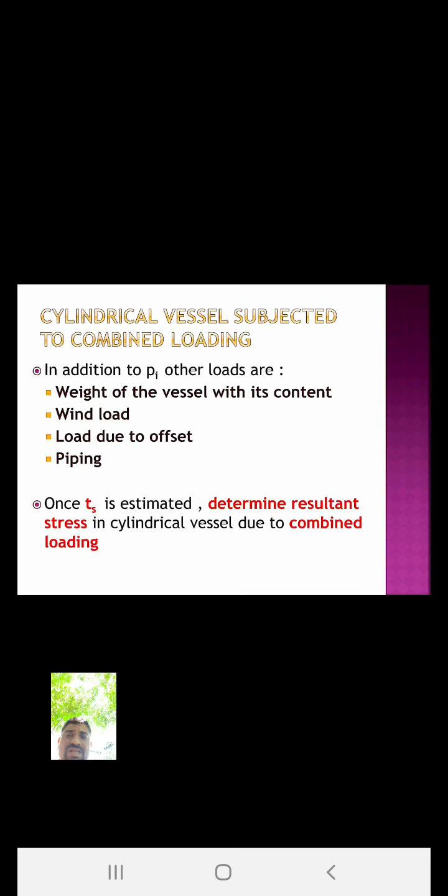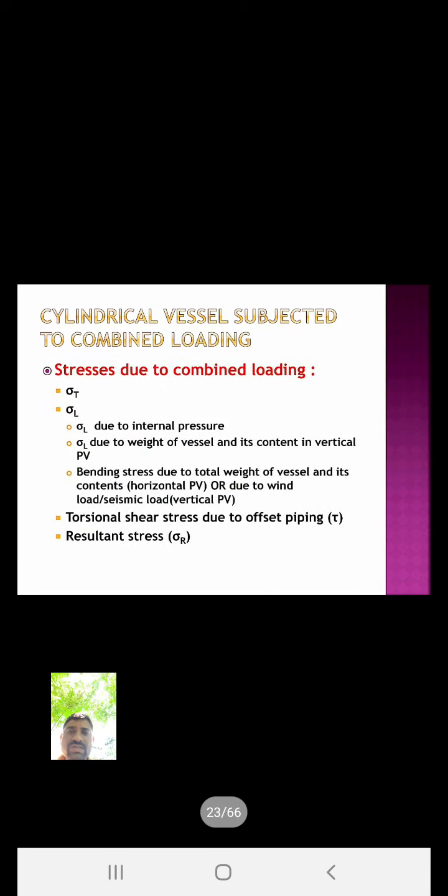First, the stress in the circumferential, or tangential, direction. It is denoted by sigma t. It is called the tangential stress. And second, stresses in the longitudinal direction.